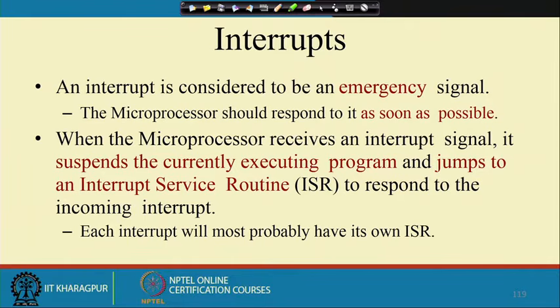This is also known as ISR in short, to respond to the incoming interrupt, and each interrupt will most probably have its own ISR. In some cases some of the interrupts may be grouped together to have a common ISR, but in general each interrupt is of a different group. As a result, it should have a different type, so it should have a different service routine.